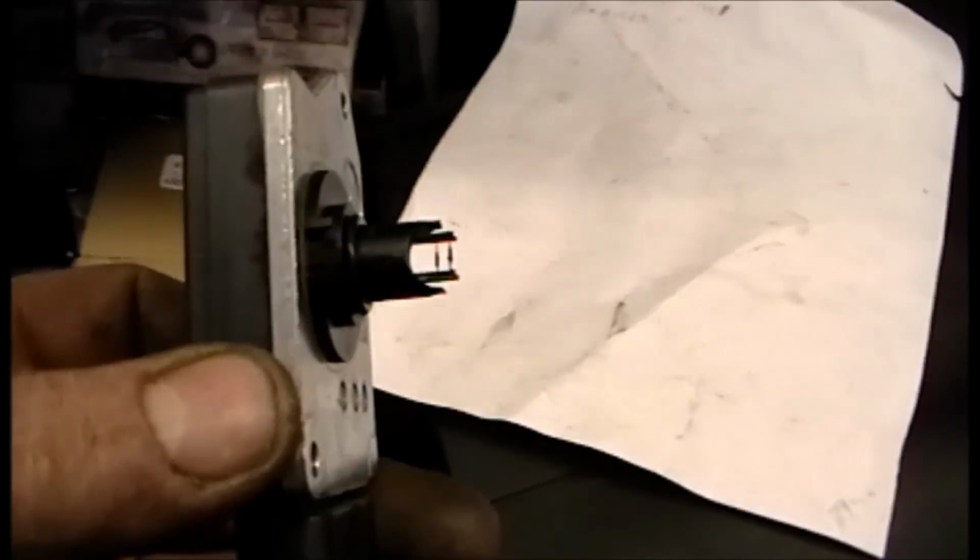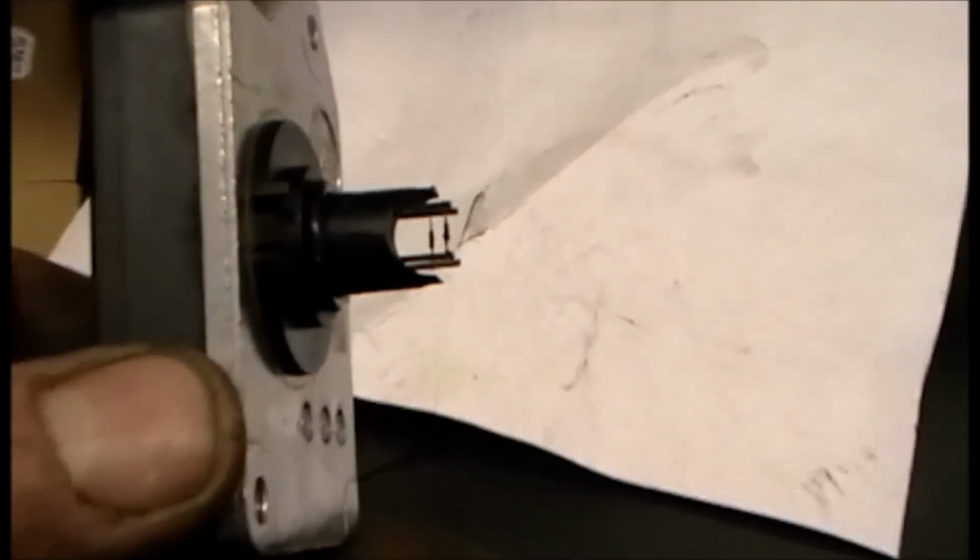If I could get a good background here, you could see how dirty all this is. Now if you see the airflow, the air's going that way, so all the dirt is going to pack across those two sensors. The lower one's your hot wire, and the one in the back is the one measuring the temperature, the cold wire. Now if you look at the other side, where the airflow's not flowing this way, that's what they should look like clean. You can see the dirt just packed around the upper one.